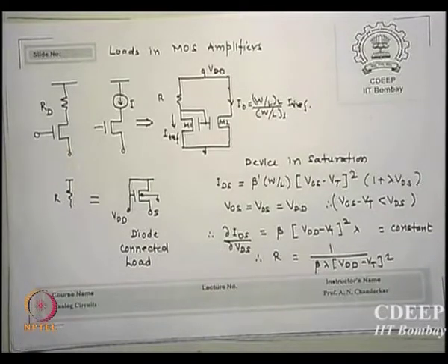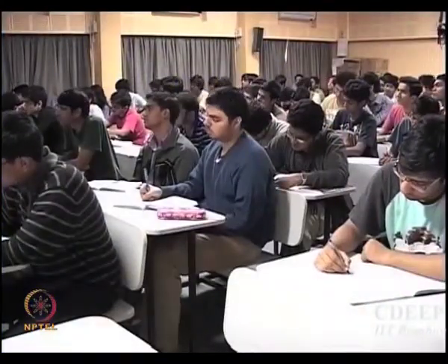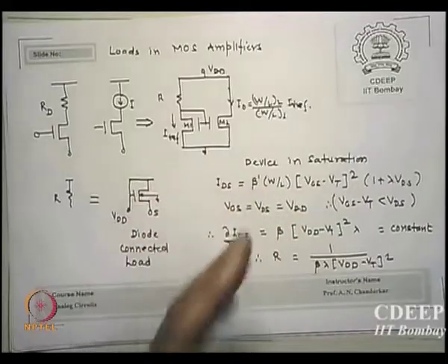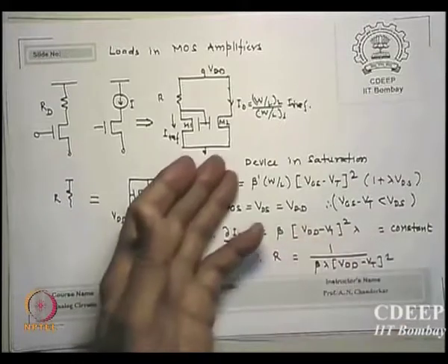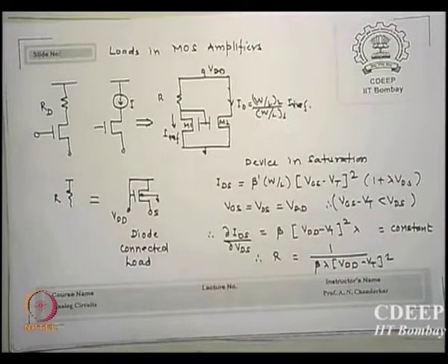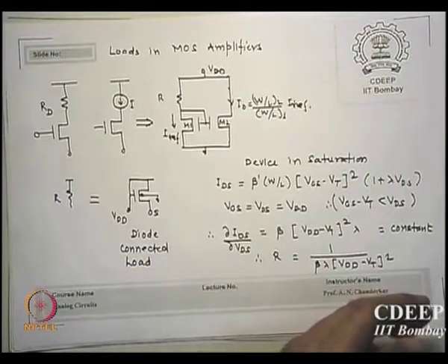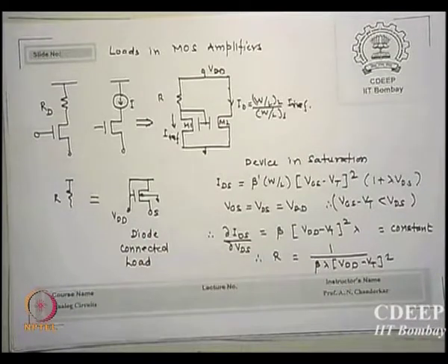How to calculate resistance? Just delta I by delta V, and the inverse of that is your R. So nothing great happens, just write equations, differentiate and get your resistance. Is that okay? Of course these equations which I write you need not write down, I just want to show you what it is. I need not have written all that, I would have directly written the result here, but I thought you should know how I calculate it. This is only to show you methods, this formula is not relevant. This is the method which I am showing of how to evaluate R in transistors.